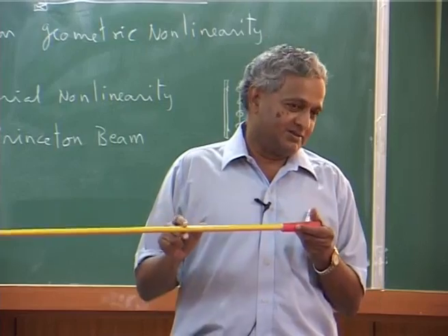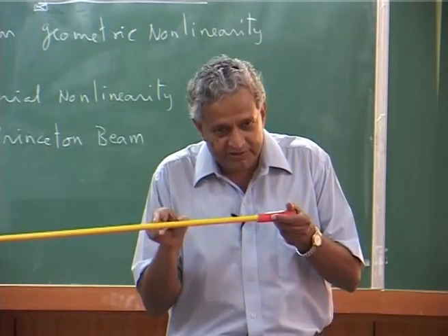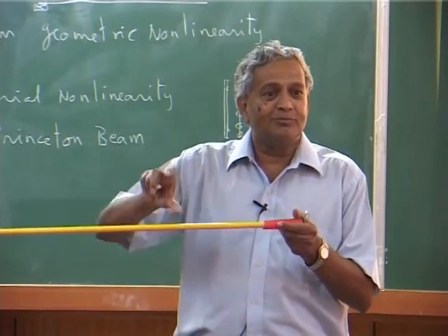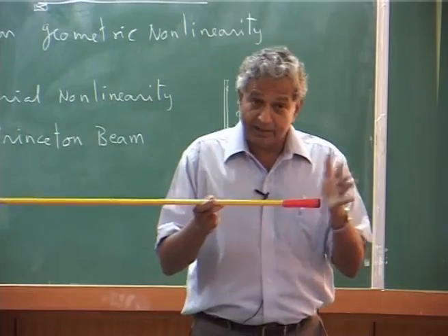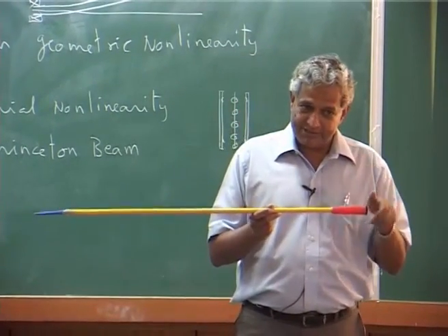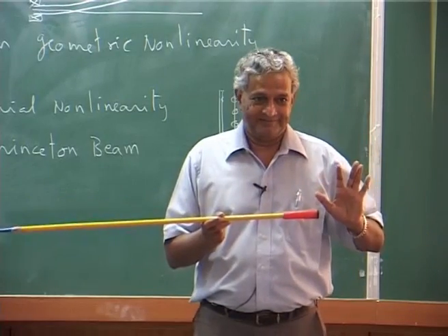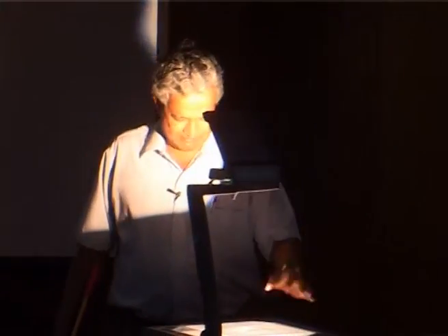It is a virtual hinge, not a physical hinge, but some point is soft, therefore it can flex about that point. But the pitch bearing is inboard. Most hingeless blades have the pitch bearing inboard, you do not keep it outside. You see that goes into construction.